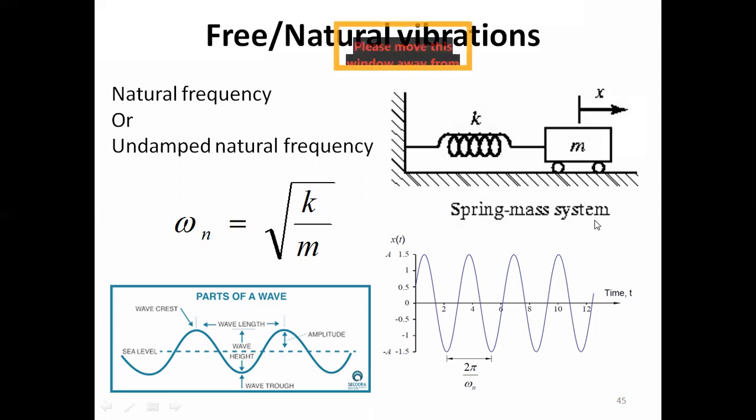It would have one natural frequency, and you could easily see that it is a 1 degree of freedom system. So simply, if you want to model a real continuous system and find the fundamental frequency, that is the first frequency of the system, then just model it as a single degree of freedom system, ignore the damping, and find the undamped natural frequency with this mathematical model.